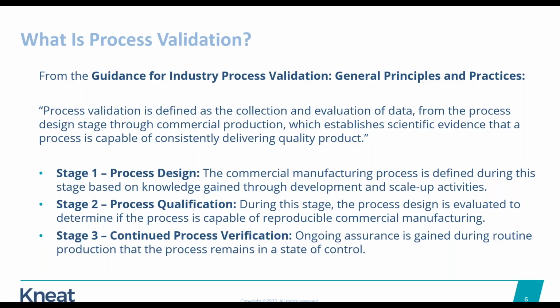And also, if you have seen the Kneat portal, there is an article on process validation in there, and you might have seen the term prospective validation. These first 2 stages are very similar to prospective validation, where you are establishing evidence prior to process implementation based on proposed pre-planned protocols. So you're gaining all of your information in stage 1, and then in stage 2, you have protocols that you will fill out as your batches are manufactured. So do keep that in mind.